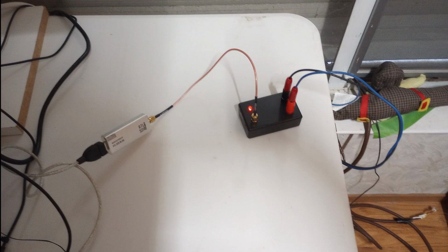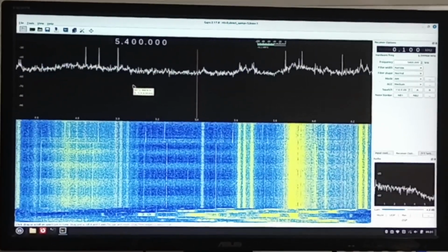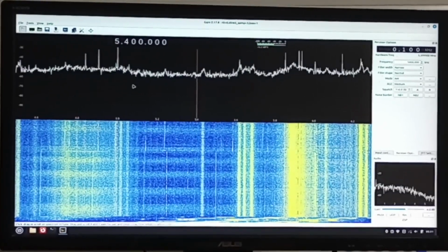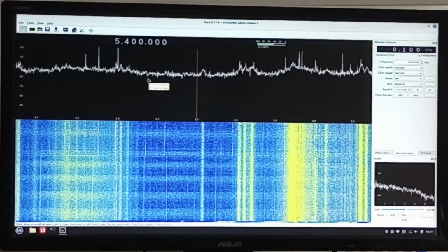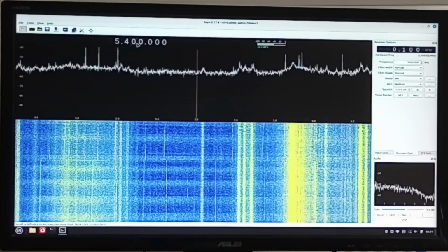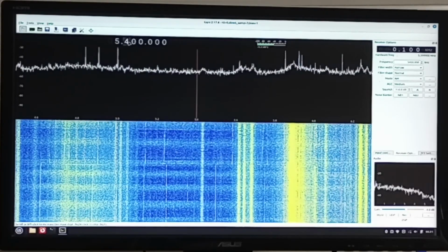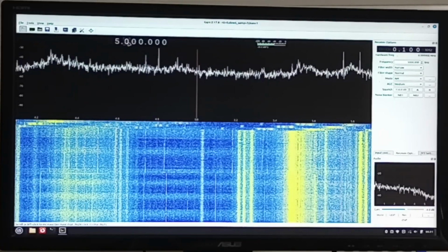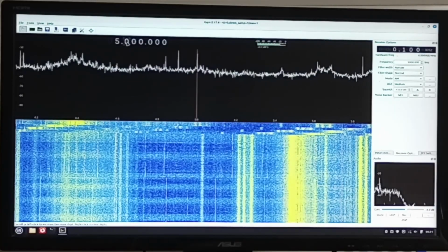Now that it's in the box, it's time to give it a good thorough testing. So I set it up and waited until quite late at night to dial around and see what shortwave stations I could get. Oh drat, there's a problem. No matter where I dial, I can still hear one of the local AM talk radio stations coming in. Obviously, the amplifier is amplifying that station up to so strong of a signal that it's overloading the input of the SDR.